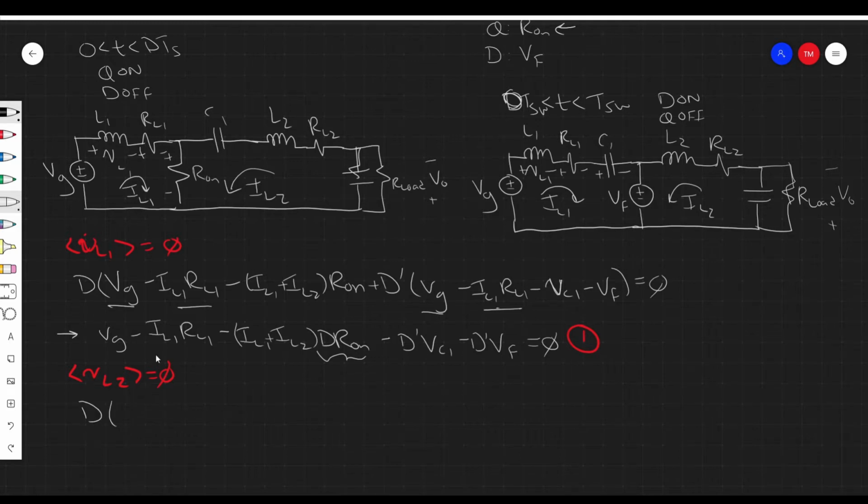Doing it in this simplified way, we think about the voltage across this inductor, right? And again, I've defined it in this direction, VL2, because we know that the current is going to flow in the direction I've indicated, anti-clockwise. So, how do we do it? Well, we move around our loop, and voltages which align with our loop are positive, and voltages which don't align or are anti-parallel with our loop are negative, right?